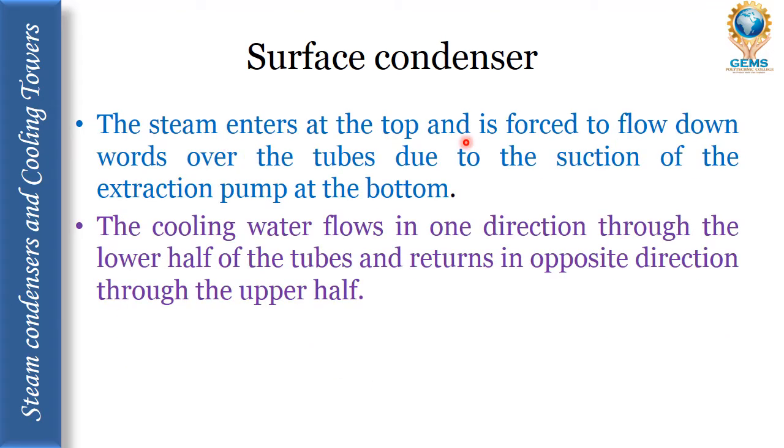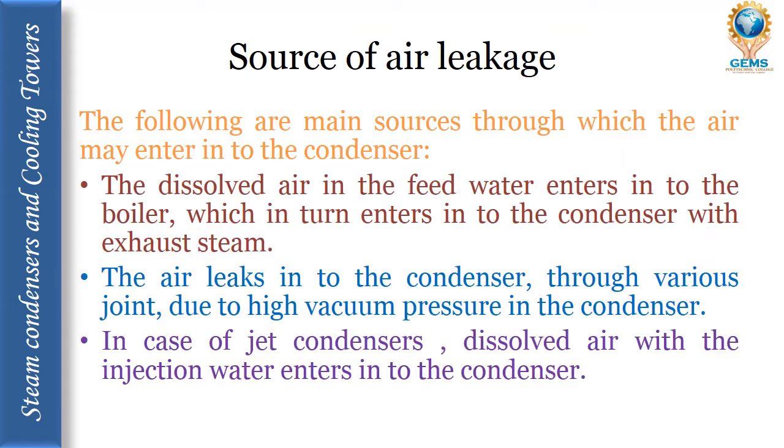The steam enters at the top and is forced to flow downwards over the tubes due to the suction of the extraction pump at the bottom. The cooling water flows in one direction through the lower half of the tubes and returns in the opposite direction through the upper half.